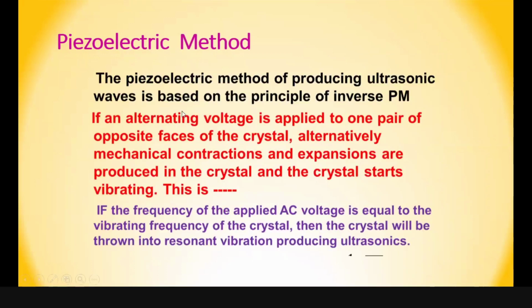The piezoelectric method of producing ultrasonic waves is based on the principle of the inverse piezoelectric effect. If you apply an alternating voltage to a pair of opposite sides of the crystal, there will be mechanical contraction and expansion inside the crystal, due to which the crystal starts vibrating. And when both the frequencies match, we get the ultrasonic waves. Fine.